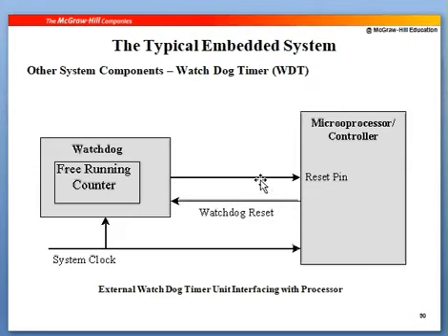So that's what happens here, and here you have to know when to enable the watchdog timer. It will be enabled by writing a 0 to this unit. You have to write to this unit before executing the firmware program.